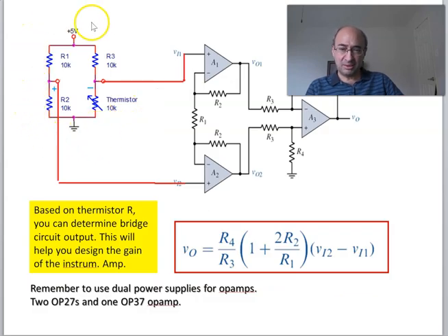This is again the bridge circuitry. It's drawn a little different. For higher temperatures than room temperature, you will get a voltage between this plus and minus terminal shown here, and you can directly apply it to the inputs of the instrumentation amplifier.